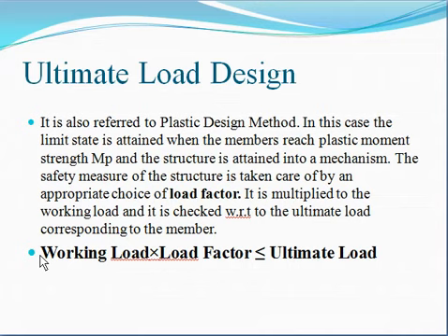Or when we use dead load plus wind load or dead load plus earthquake load, in that case also the load factor is 1.7. And in case of a combination of three loads, that is dead load plus imposed load plus wind load, or dead load plus imposed load plus earthquake load.